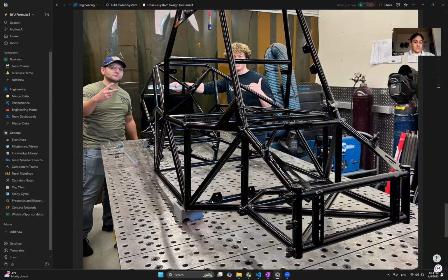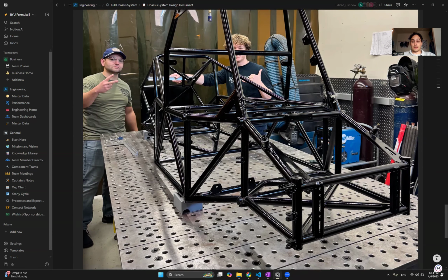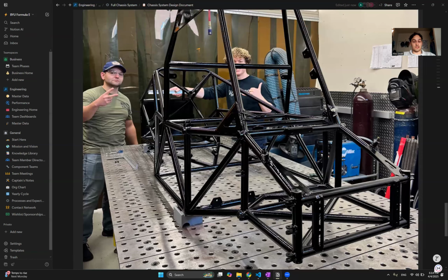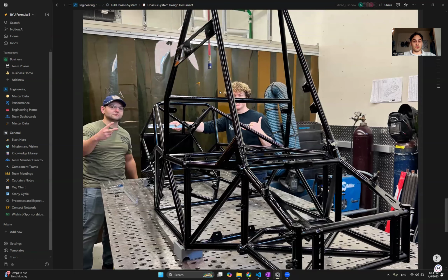That was a feature that we designed intentionally so that we could weld the frame faster by having these two squares on different sides of the table, have two welders going at the same time. So that's just a key feature of our design. There's also this rear box here that was kind of a headache for us in designing, and that's something that needed a lot of testing and FEA, and that we hopefully will get some more validation of when we do physical testing when the car is driving.